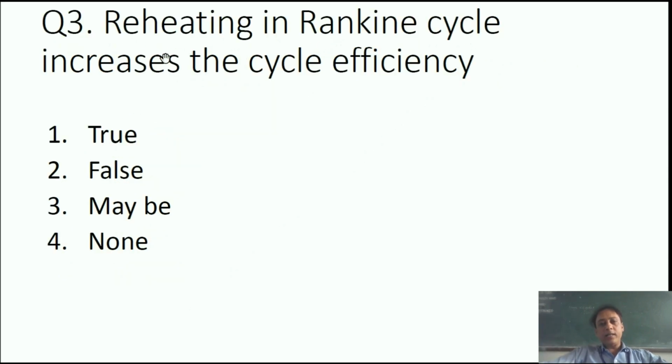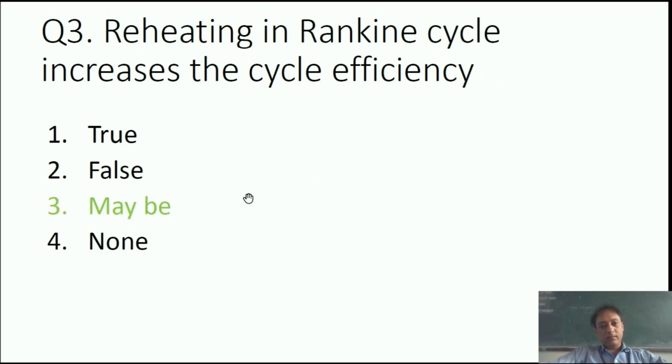Reheating in Rankine cycle increases the cycle efficiency. True, false, maybe, none? The answer is maybe. I already told you that by the help of reheating, mainly we control the dryness fraction. The efficiency can increase or can reduce also, depending on whether the reheating is performed properly or not.